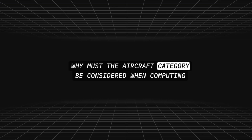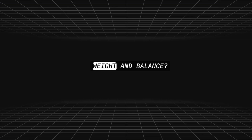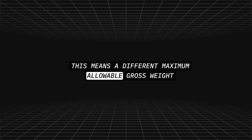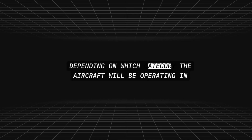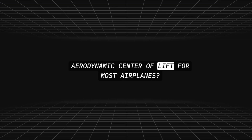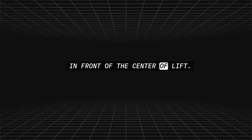Why must the aircraft category be considered when computing weight and balance? Some aircraft are certified in both normal and utility categories. This means a different maximum allowable gross weight depending on which category the aircraft will be operating in for that day. Where is the center of gravity located in relation to the aerodynamic center of lift for most airplanes? In front of the center of lift.